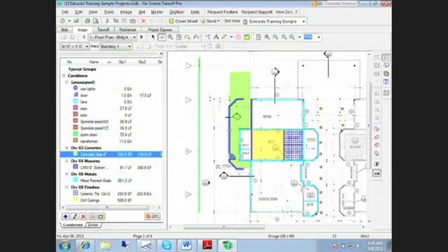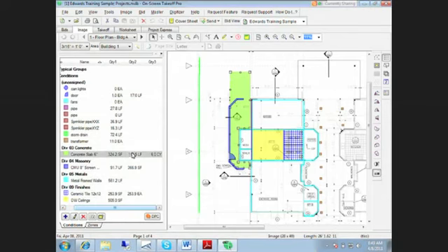That's the kind of thing where a tool like On-Center really shines. If you've got an area that's 10 by 10, it's pretty easy to calculate the area, right? But if it's an odd shape like this, with corners and diagonals, all you have to do is trace along that area, and On-Center will calculate that. When I click on that, you can see it's got handles all around that shape, so I can extend it. Over on the left, the quantity is 324 square feet, 116 linear feet, so the perimeter of it, and then 6 cubic yards.